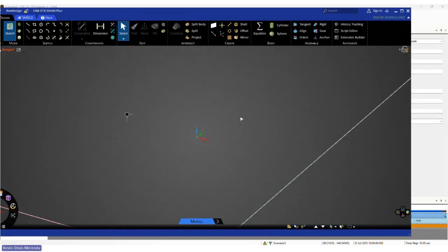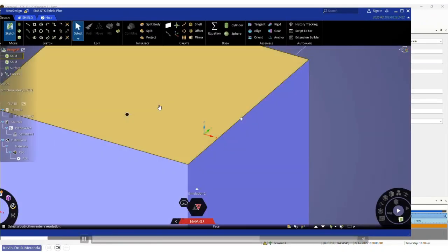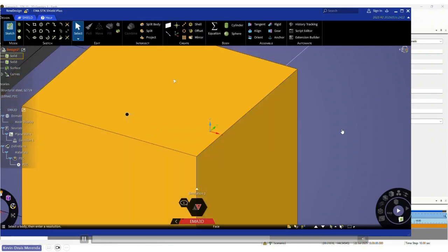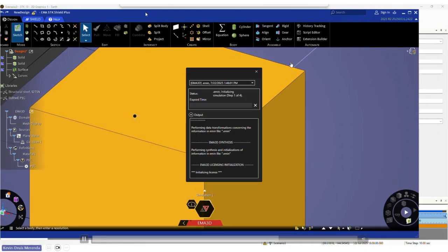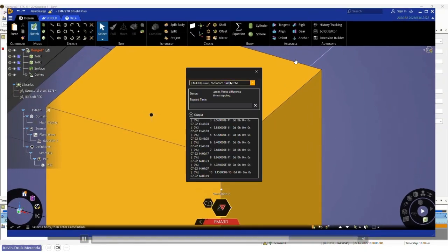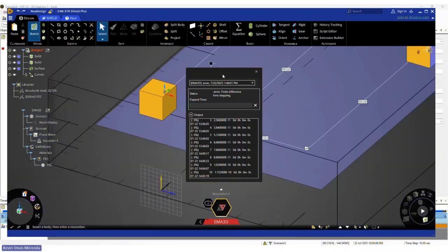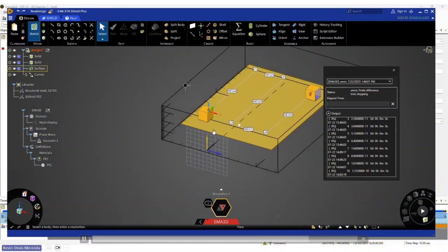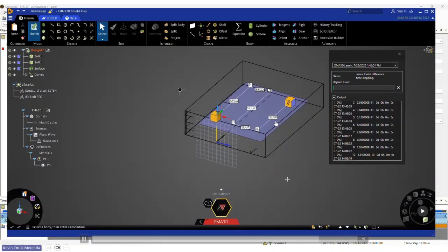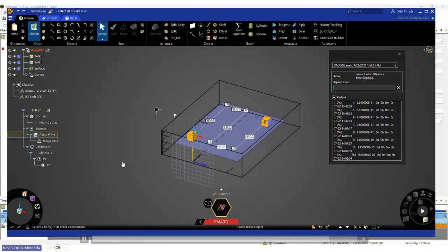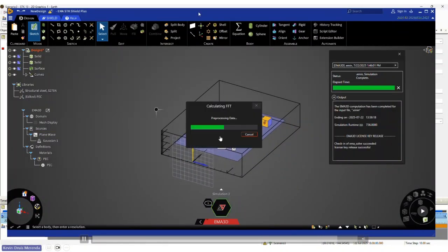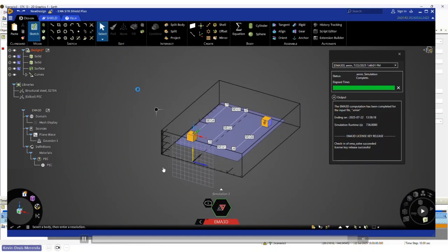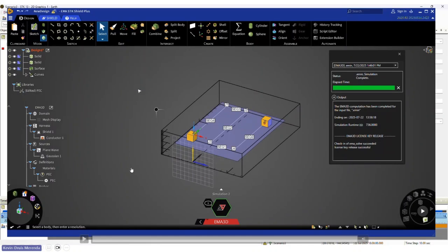And then the tool pops up. Automatically, we create the geometry. So these are the electronic boxes. And then we have the cables, and we assign the harness properties onto the tool. So this is how we're using the transmission line model. We're not actually solving this in full wave, to make these simulations much quicker. And we're shining this electromagnetic wave, this Gaussian pulse, onto the system to get the transients that are induced through the shielded conductor that we've applied on here.